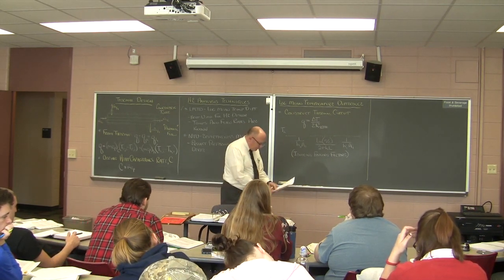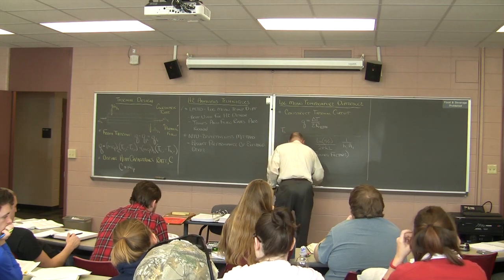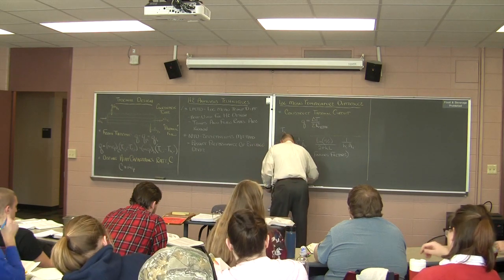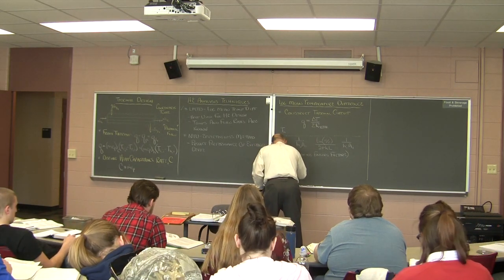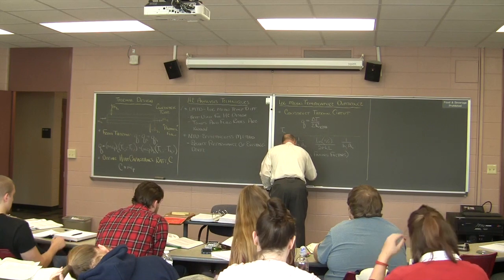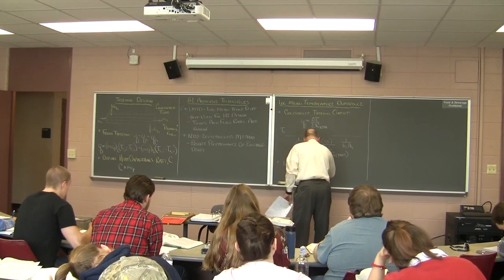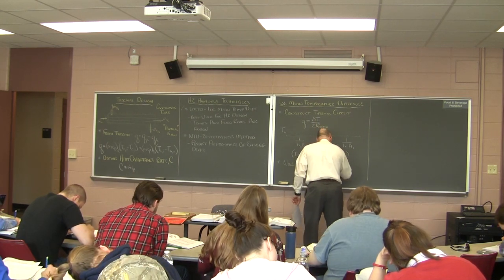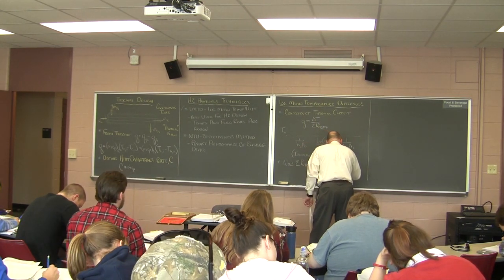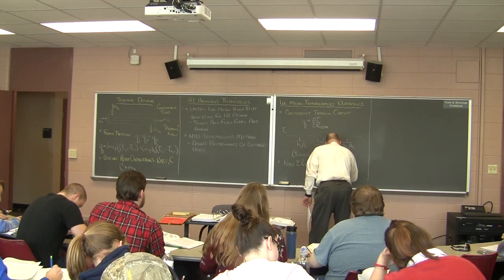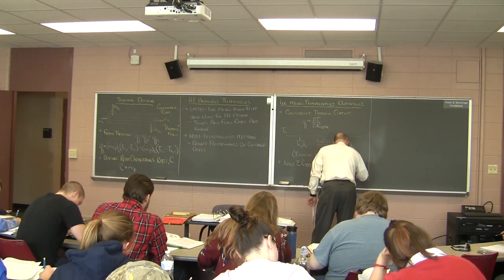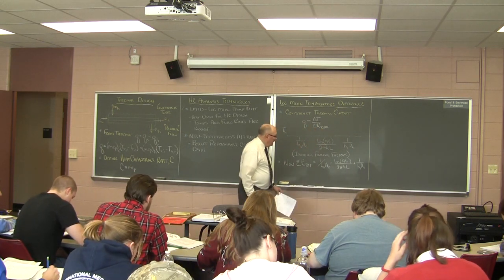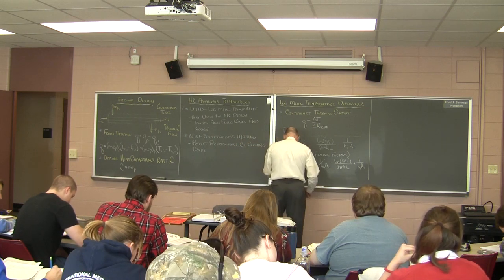All right. So having said all of this, the sum of our total resistance is going to be equal to 1 over h_o A_o plus the natural logarithm of the ratio r_2 over r_1 over 2 pi k L plus 1 over h_i A_i.